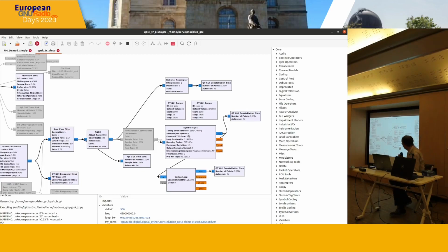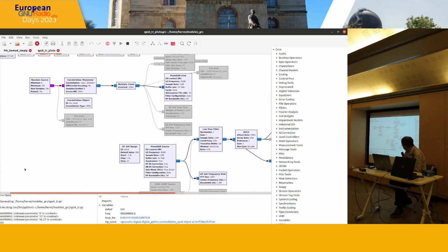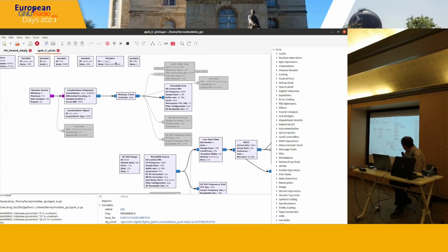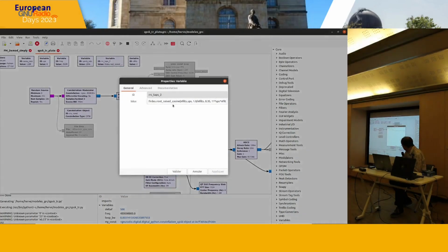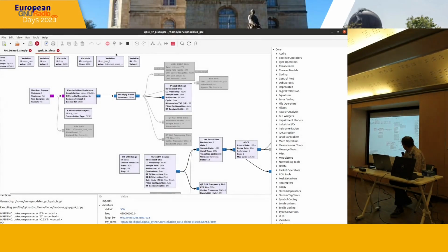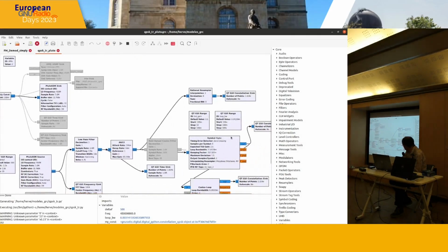And the filter, that's another problem also. You see this filter, I've designed the filter here. If you don't take the right amplitude coefficient of the filter, which is used inside the symbol sync, you'll see that you'll lose the lock as well.